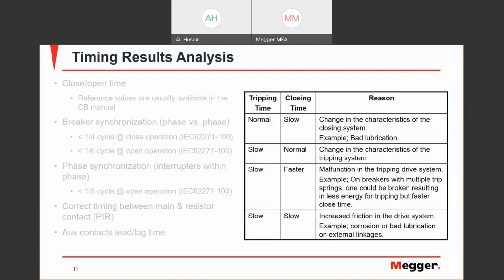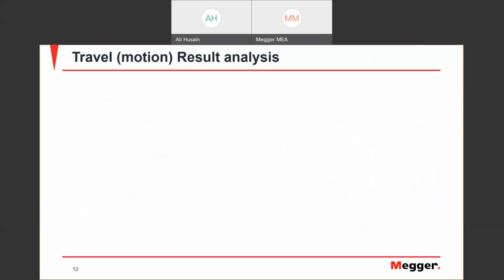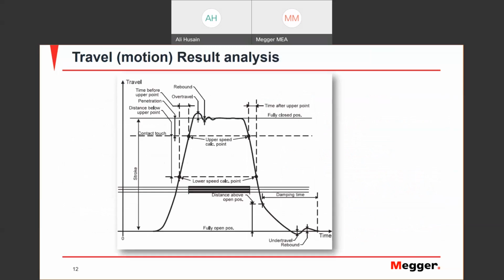Now, usually from what I see within our region, it's usually just the timing test that is done. But the standard not only recommends a timing test, it recommends timing and travel at the same time. The travel test, or motion test as we call it, is very, very important to be done. It gives you more information than the timing test,